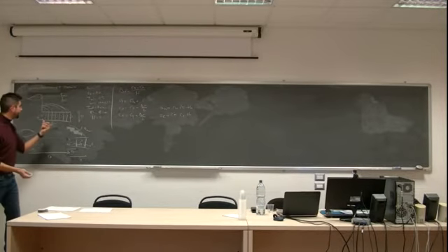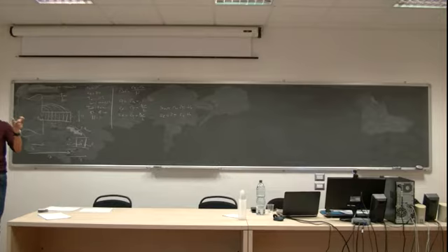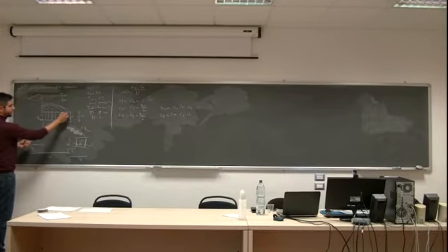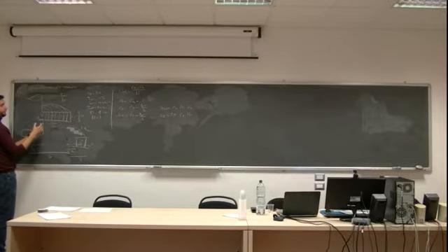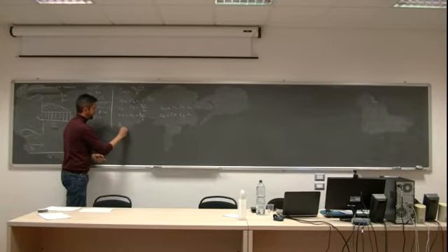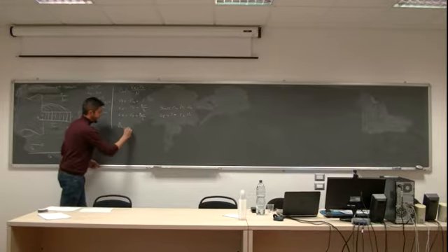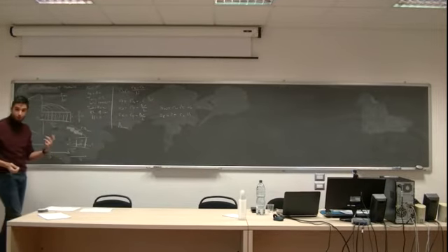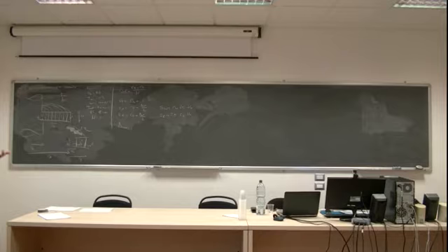Now, each node has a different surface for convection also, because these nodes have more area in contact with air than the first ones. That's the area of convection. That will depend on i. It will depend on the position. That's why it's very important that I give the computer the information on where you are, because depending on where you are you have one geometry or another.